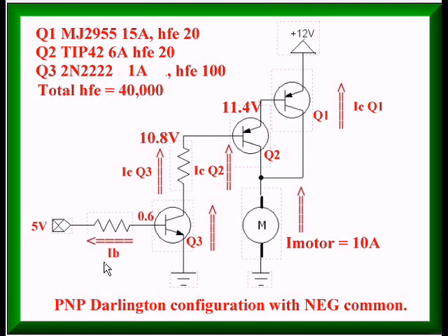As far as IB goes, use with an Arduino, use about 2.2K. I don't even bother to calculate these. They're so easy to use. You will have to watch the value of IC. You're going to have to drop about 10 volts. Okay, let's do this.